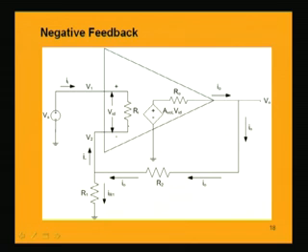The OpAmp input resistance will not have the same value of Ri; it will have a different value. So let us name it RID, the input resistance of the OpAmp. Now, because of this negative feedback, we want to find out its effect on the input resistance.